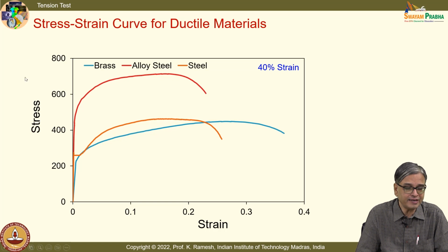And you have a difficulty. Can you locate where it demarcates from elastic to plastic? There is no demarcation. There is a clear demarcation in the case of a mild steel, which is absent in the case of an alloy steel. And if you look at the maximum strain, they are similar. There is a small dip in this.